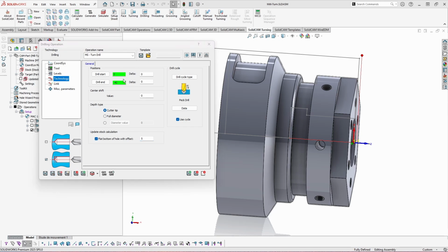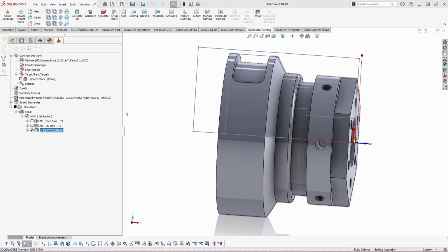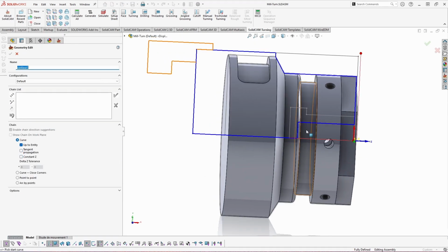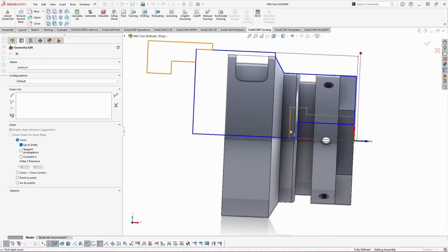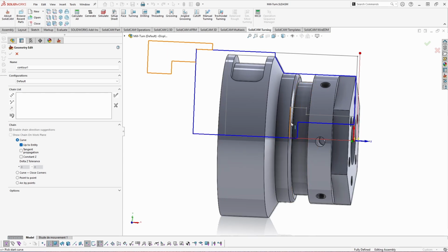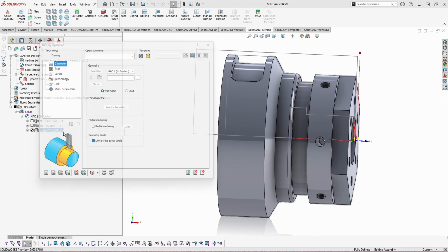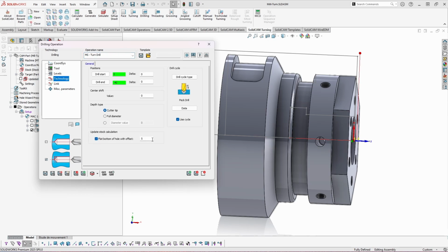What this will do is when we start creating our turning job geometry, our updated stock will no longer have the angle, it will have the flat bottom. And of course, you can see that it is offsetted for 5mm from the drill depth. This is how you can control your updated stock after your turn drilling job by using this simple field here.